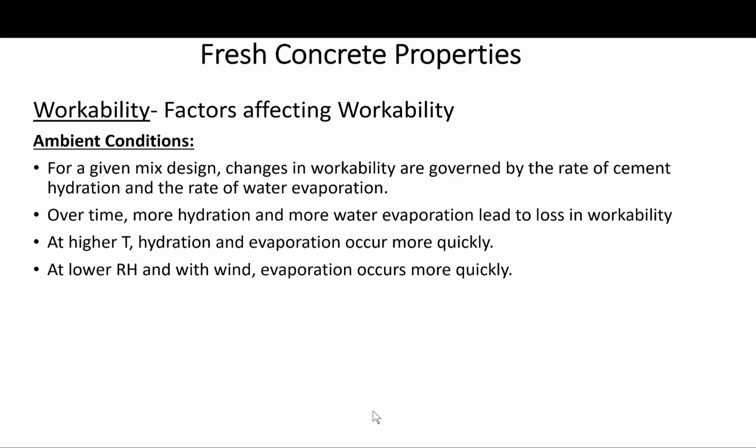All right? But on the other hand, there is also some evidence that, at least for short times, workability itself is not affected by the temperature. So you have to investigate both evidences. So remember this, where temperature may be a factor, field tests should be carried out with the specific materials in order to determine the temperature effects for a given job.